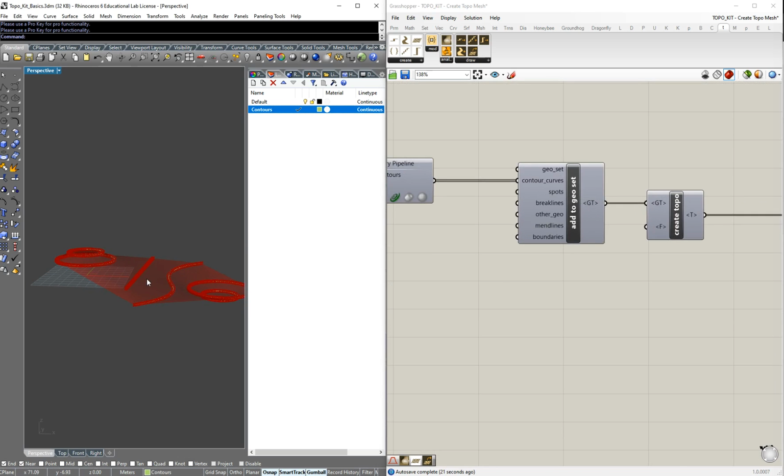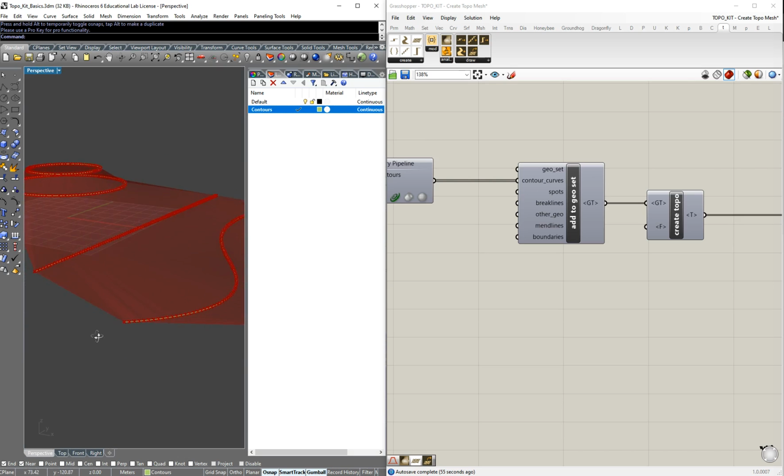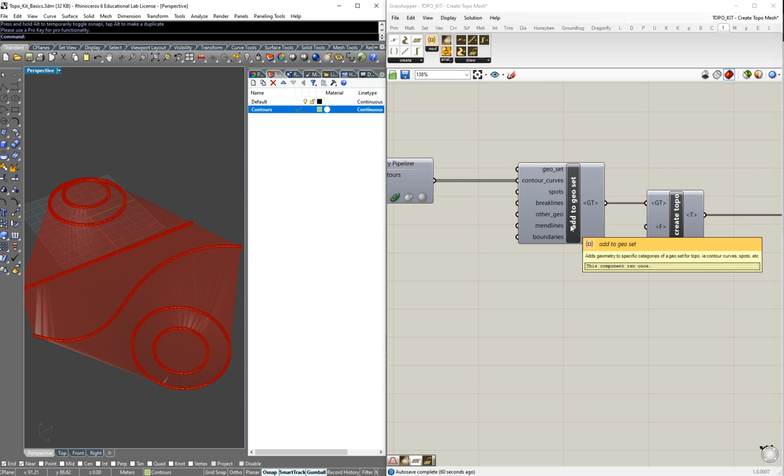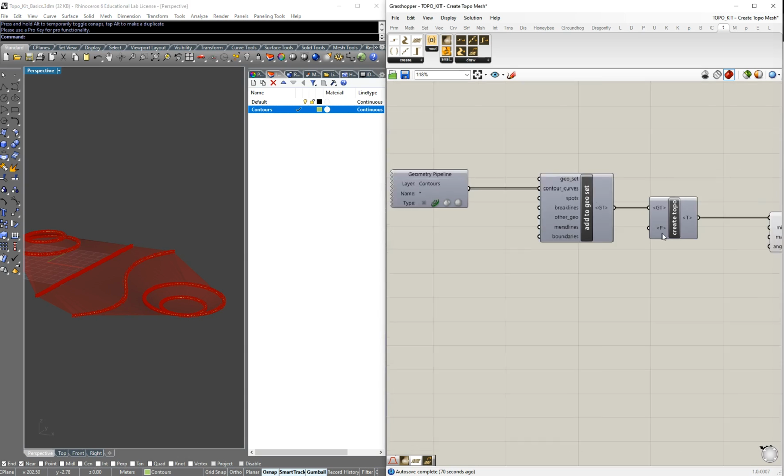If you change in the layer, let's imagine you are in your contours layer, you change this line and you change the height, let's make this dramatic, the topography will change. If you change the height, the topography will change accordingly. Also, if we go to the top and change, let's imagine, the orientation of this and also this, perhaps like that, or you extend it or you reduce it, everything will be modified. So you have a quite interactive topographic information. If you have your own topographic contours or breaklines, then you can just bring them here, and then you can modify the topography and the terrain will be automatically modified.